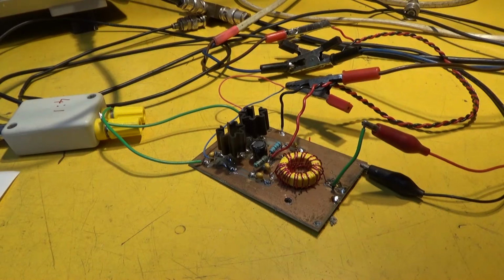local medium wave or long wave transmitters, and there are a fair few of those around here. We've got 198 kilohertz Radio 4, which is 500 kilowatts, and that's only 30 miles away. And on the same site there's 693 kilohertz, Radio 5, also I think at around 500 kilowatts. I believe those two were mixing in the amplifier and producing spurious signals, which were appearing in the 160 meter band.